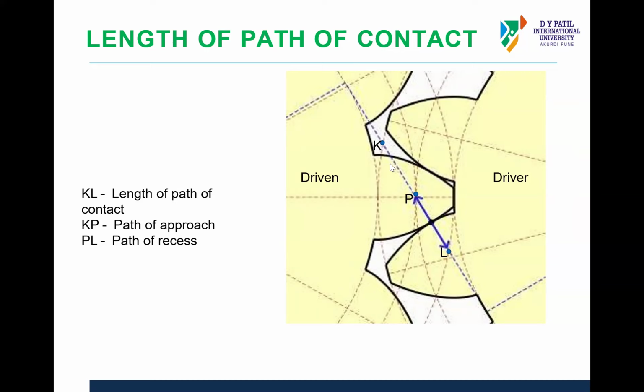And just look at the gear surface which we have. This is the involute system, okay, which has a straight profile and constant pressure angle. This surface pressure angle will remain constant throughout the surface. Okay, whereas in case of the other pairs, epicycloidal or hypocycloidal, this pressure angle may vary. Okay, and that's why the wear and tear is more. We can say interference occurrence in case of this involute surface is more as compared to cycloidal gear. Okay, this is the difference, and all about the pressure angle related to these two types of tooth surface, involute and cycloidal. Okay, so we'll stop here.